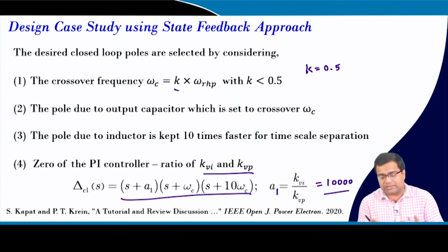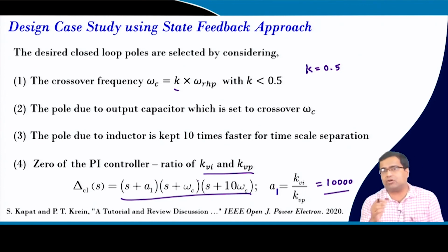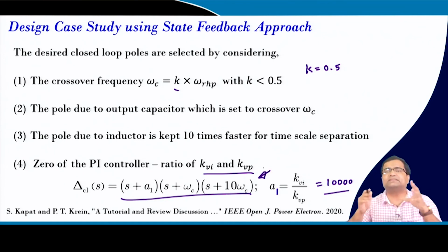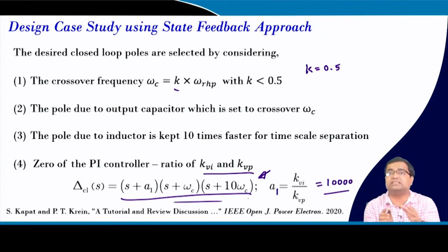Here we are only considering a current loop gain, which you may not need to change in analog control. In fact, in analog control we will use offline design, because we do not generally do real time tuning. In offline design with this state feedback approach, we can simply set a current loop gain, and this approach can improve the performance much faster as well as much better, because there is less overshoot compared to the traditional output feedback approach. So, this method is very useful for design of current mode control.